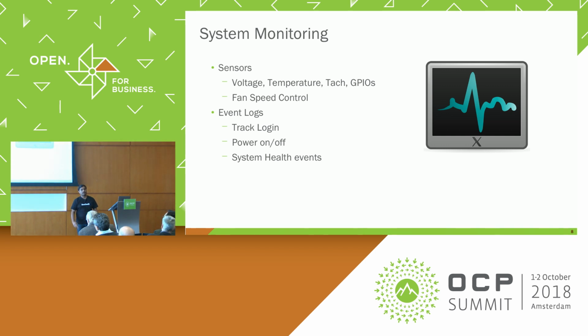So we want an ability to continuously monitor the hardware and find if any error is there, and take remediation action. Say if a temperature sensor is not proper, just spin up the fans. Or if some threshold is crossed, shut down the system and log the failure, so that when a technician goes there, they can collect the logs, identify the failure, and at least understand what actually happened on the system, what component failed or why it failed. Is it a problem with the hardware, or is it some kind of environment problem in the data center itself.